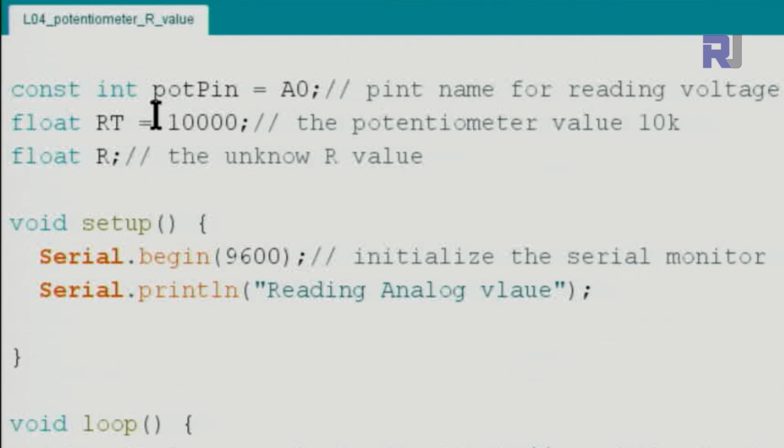In this case, this is a 10 kilo ohm. And the B, by the way, at the beginning, B means linear. For our case, this is linear, which means if this is 10 kilo ohm, the middle will be 5 kilo ohm and so forth. But for audio and for other logarithmic types, we will have A and other letters that correspond to those. So B means linear.